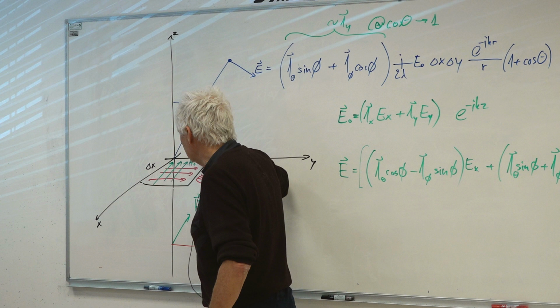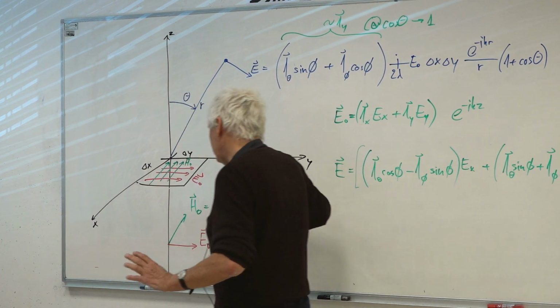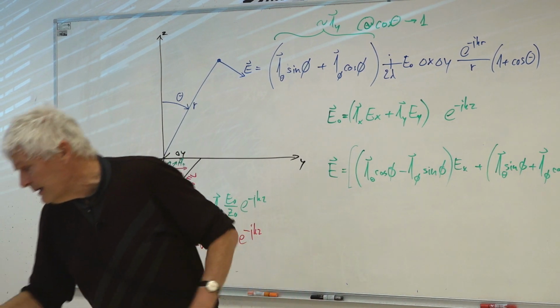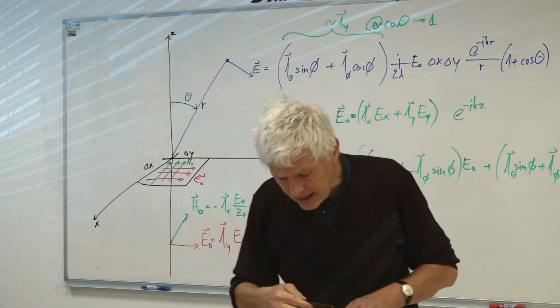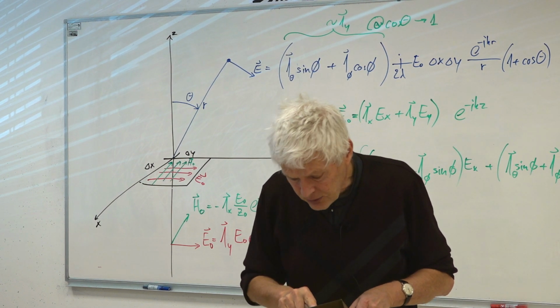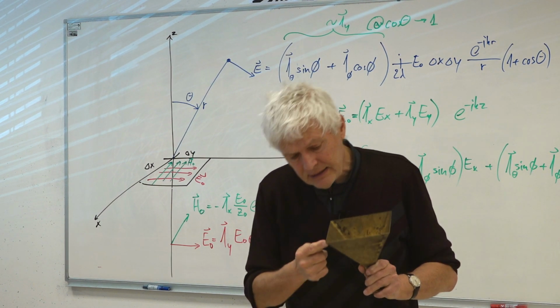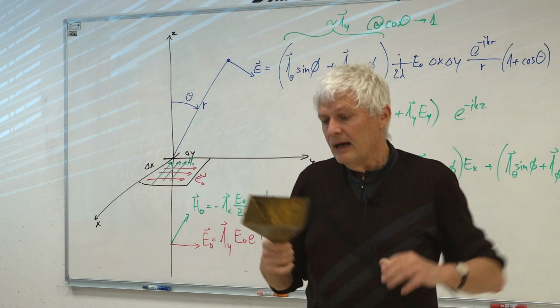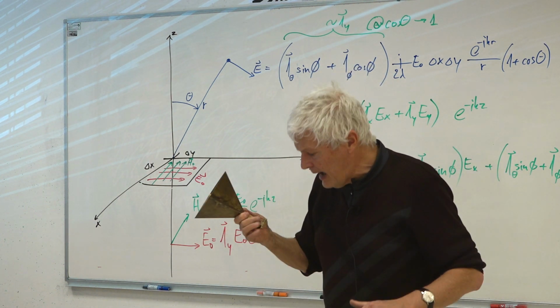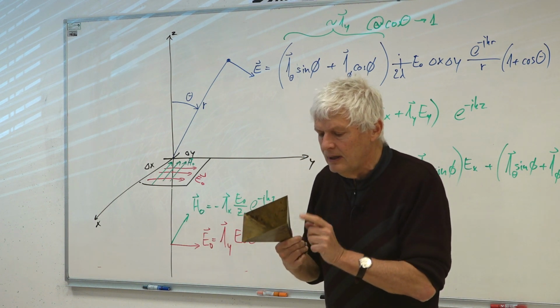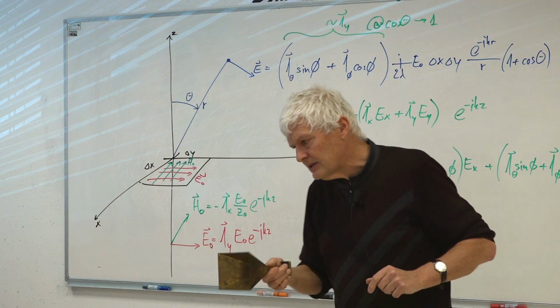There are no currents flowing in the screen. If there are currents flowing in the screen, then we have problems. Also with this antenna, yes, there are small currents wrapping around every edge here, and also here there is some radiation here and some radiation here because of these currents wrapping around. But as long as this thing is large compared to the wavelength of our waveguide, these currents are small. And we are going to neglect these outside currents.